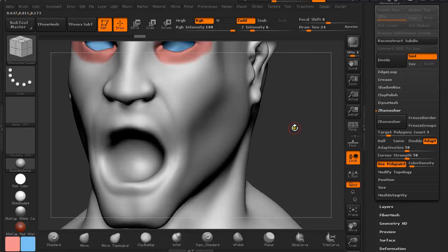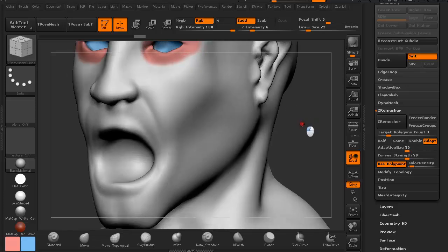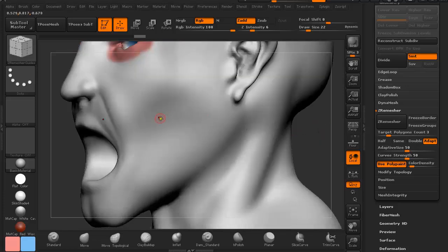So with the size of the brush, pressing S again, you can set how close the points of the guide are going to be. So we have something like this, and we can see we create the guides with this kind of distribution of middle points, and if we resize the brush, we can see it's more rigid. It has fewer points in between.